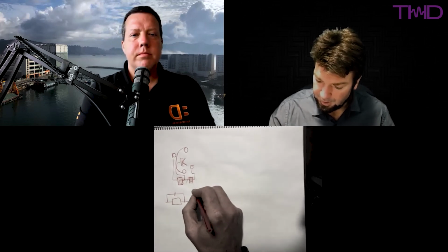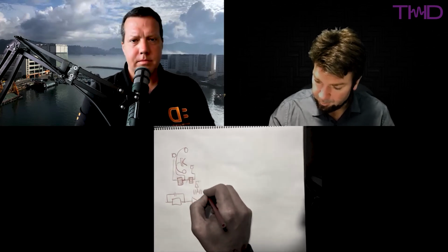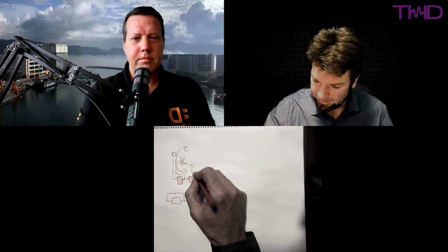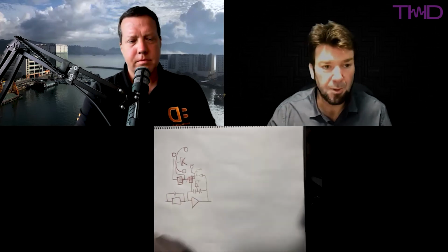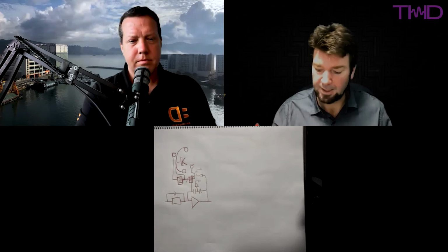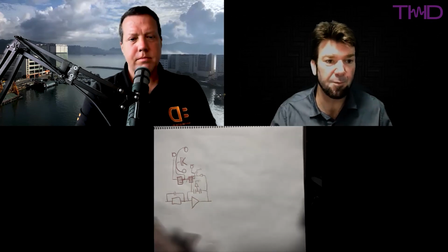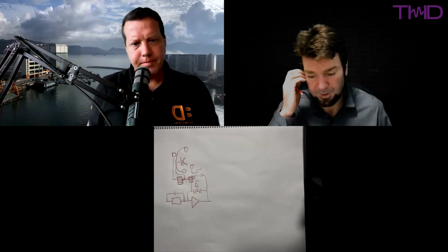They often do this type of thing, actually, a boosted notch, as it happens. I've run out of space to do the other half. People in electronics will know what I mean. You have the resistors there. It's all overlapped. They have some kind of electronic filter, and that's what Bose have, basically. They have a few other tricks too, but ultimately the feedback filter is this electrical circuit that has different output at different frequencies, and you can create the function that you want with it.